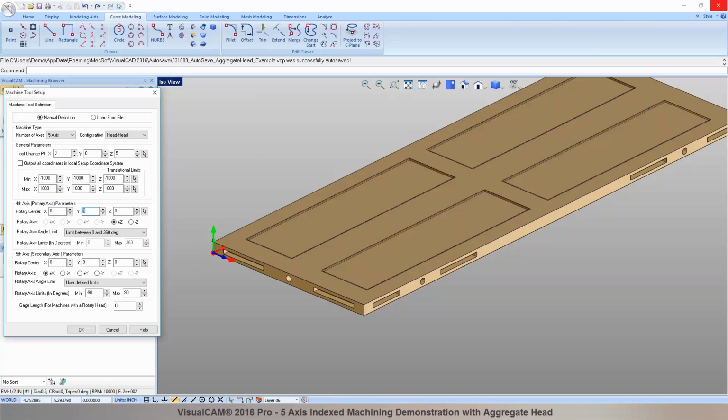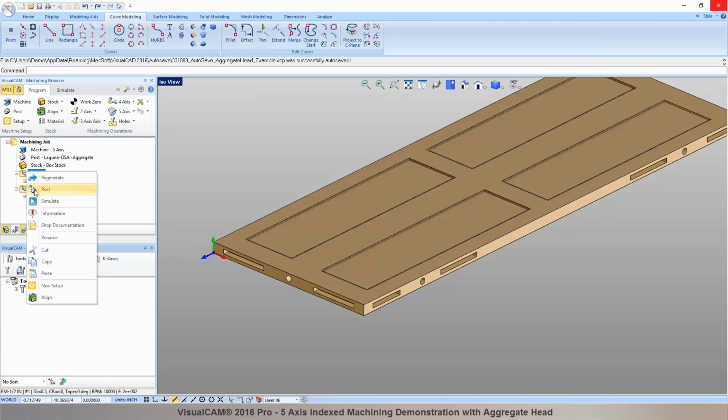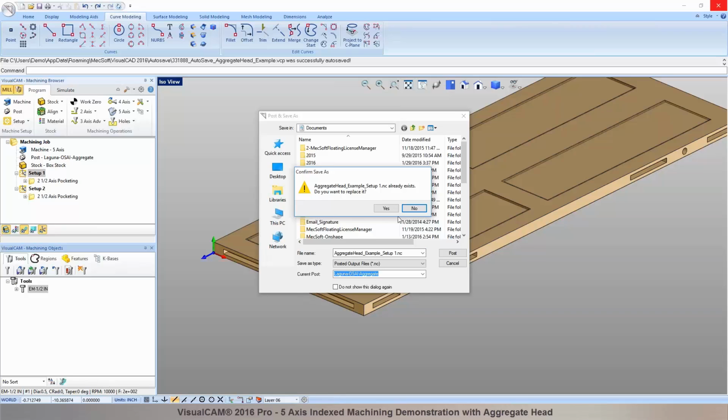So you could say maybe -5, for example. Right? So this could be the location of the spindle center when the tool tip is over here. Right? Mm-hmm. So when you compensate for this and post-process it, the posted code will automatically compensate for the offset distance as well.